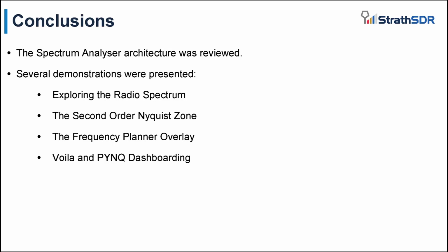In conclusion, this session presented a review of the Spectrum Analyzer architecture. The Spectrum Analyzer was then used for 4 demonstrations. These included exploring the radio spectrum, using the second-order Nyquist zone, working with the frequency planner spectral overlay, and achieving on-target application deployment with Voila and PYNQ dashboarding.